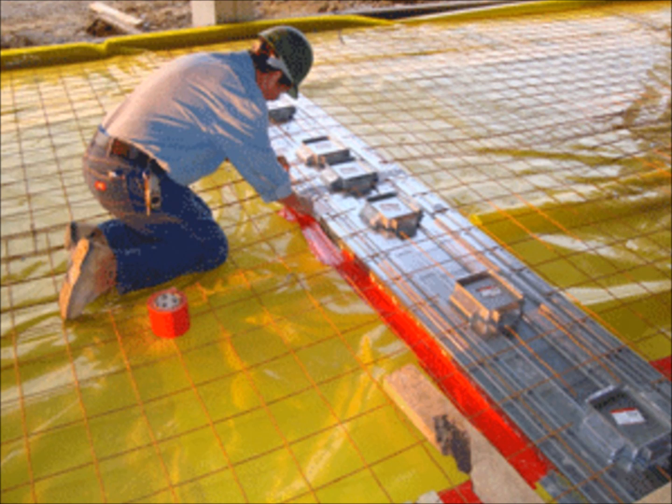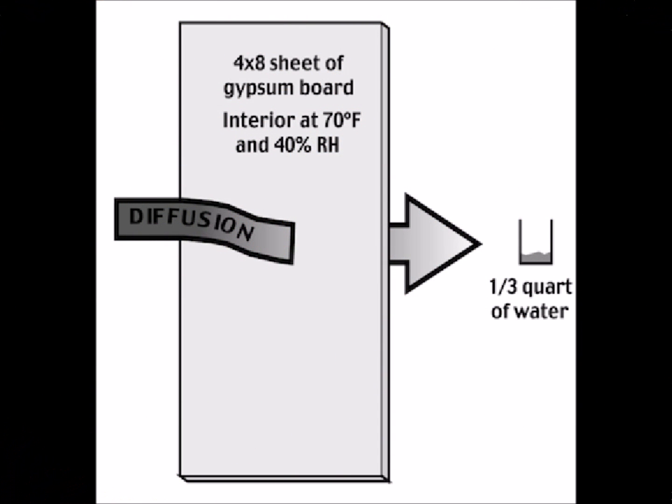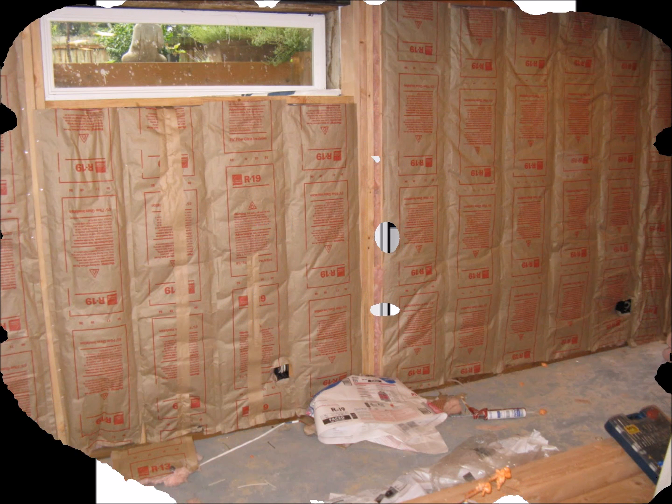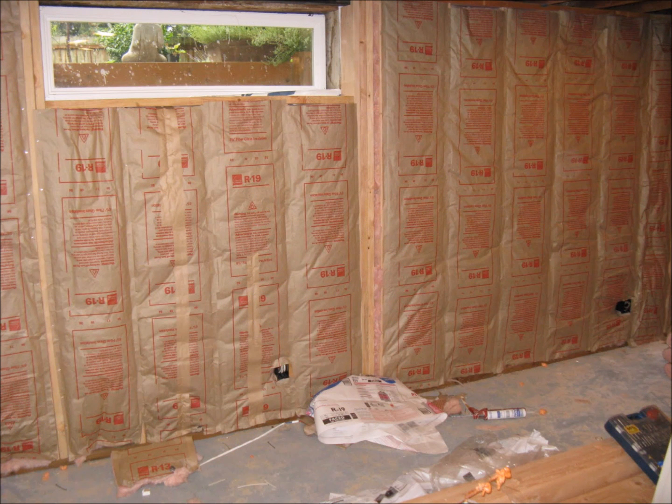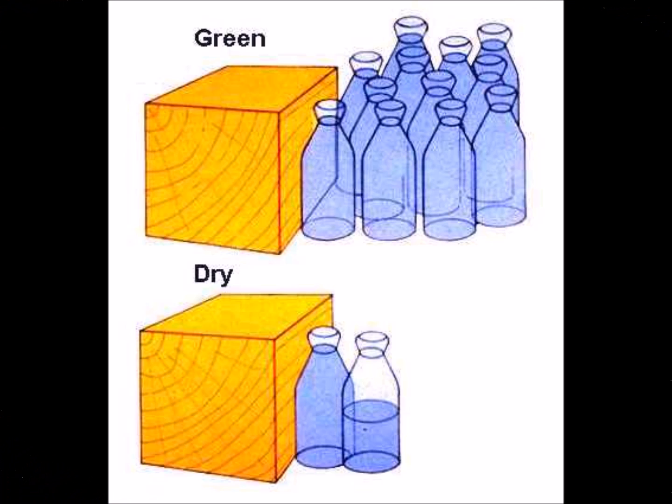With wood frame homes, which are very common in the US, wood grows thicker with increased moisture, not longer. It also shrinks along its width, not its length. When dealing with manufactured wood products, try to compensate for this by using cross-graining and fiber orientation or resins and waterproofing materials. They tend to expand in all directions rather than just one. This expansion and contraction will cause separation and allow water and/or water vapor to enter through the gaps.